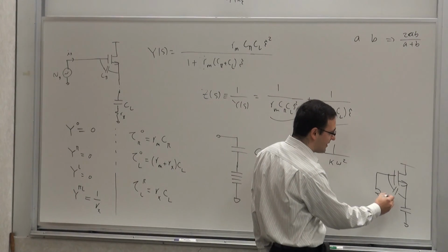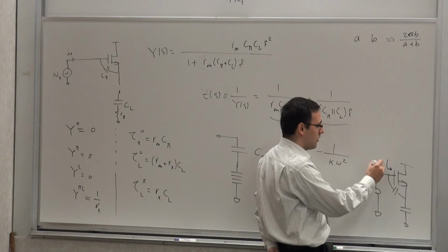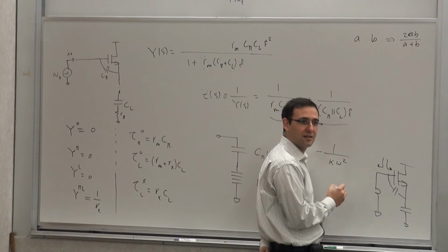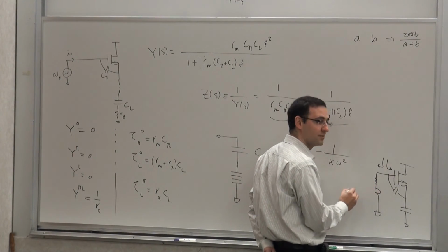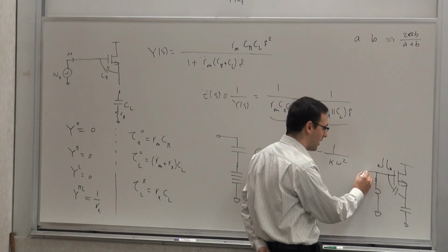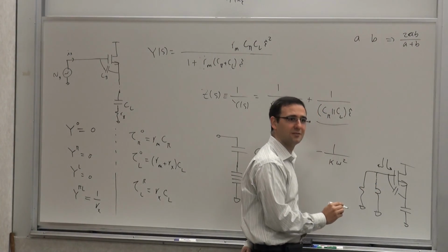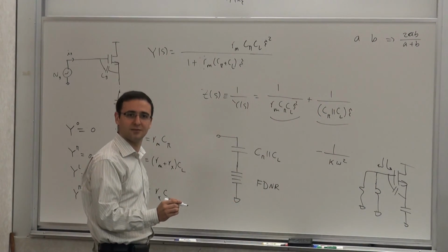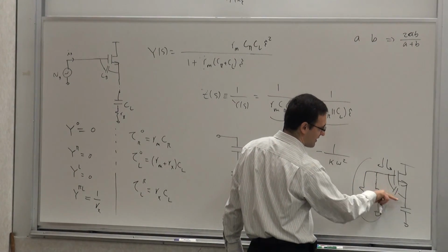What you have is capacitance here, right? And inductance on this side, and you have negative resistance on this side that will cancel the loss, or the positive resistance on this side. It can cancel if you design it properly. And this thing can oscillate if you attach an inductor to it, because this negative resistance cancels the loss.